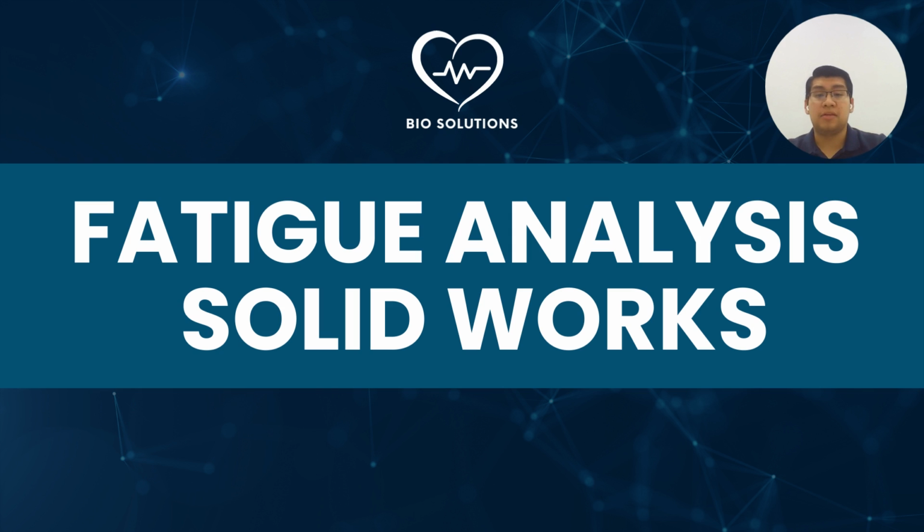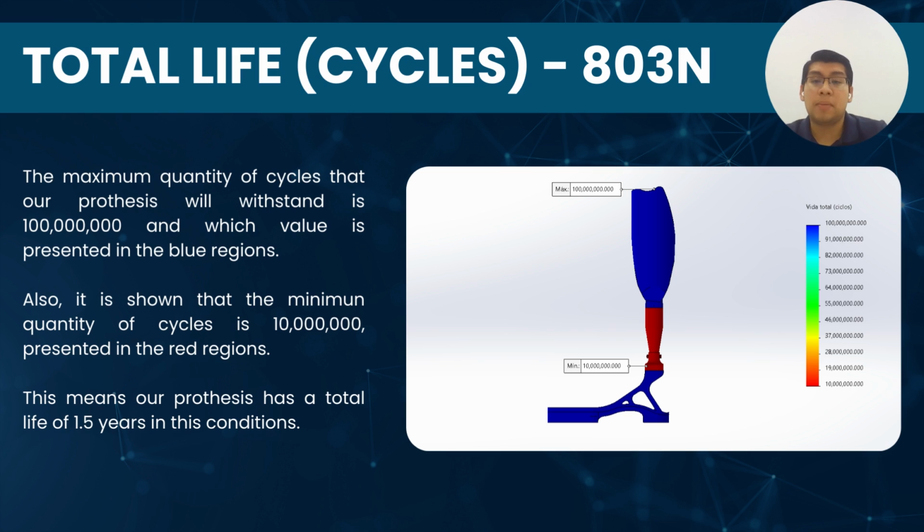Now, for our fatigue analysis, we consider testing the total life and the damage percentage. For an applied force of 803 newtons, we can see that the maximum quantity of cycles that our prosthesis will withstand is 100 million, presented in the blue regions, and the minimum quantity of cycles is 10 million, presented in the red regions. This means that our prosthesis has a total life of 1.5 years in these conditions.